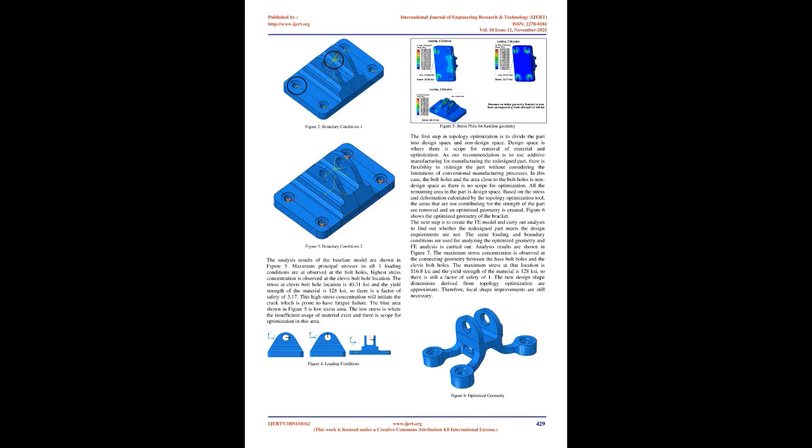To prevent the optimized structure from ending up with the full design volume as a result when searching for its maximum structural stiffness, we need to impose a volume constraint. Another possibility is to minimize the volume, as in equation 8, where V0 is the initial volume. Two common solution methods to solve the topology optimization problem are the optimality criteria method and the method of moving asymptotes.